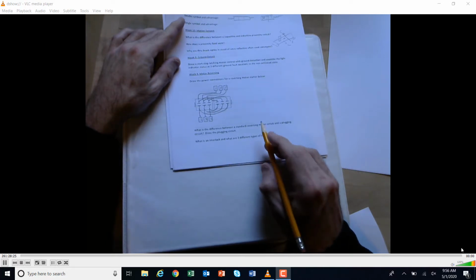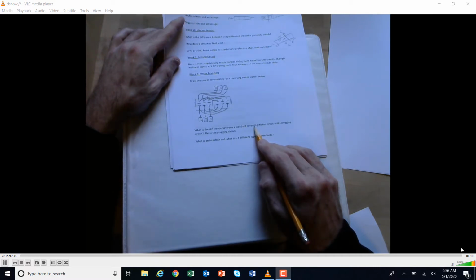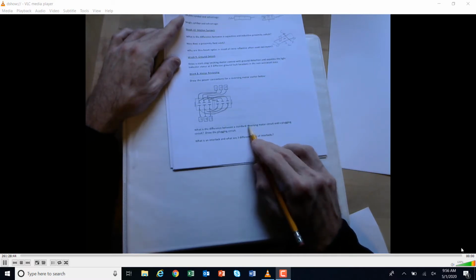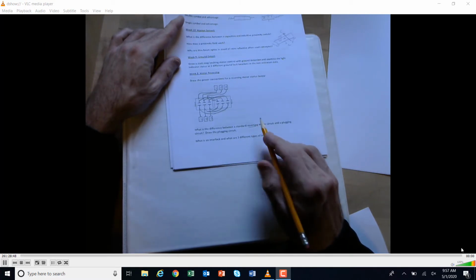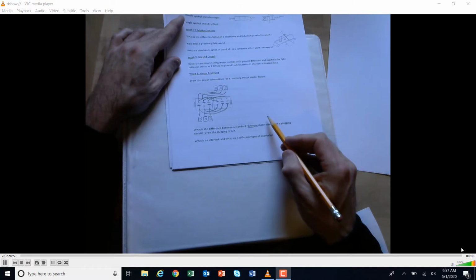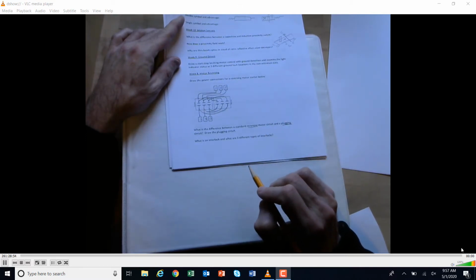So for reversing, you would have to hit stop, and then reverse it. Hopefully you would stop it and let the motor come down and stop, and then at some point later on you might want to run it in the opposite direction. I don't know in that case if you just want to automatically go from forward to reverse. If for some reason you want to go from moving forward and slam it in reverse, that's when you would use a plugging circuit, okay?